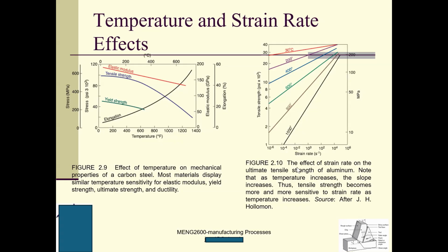So here is the strain rate. This is the tensile strength. The strain rate has a very obvious effect on the tensile strength also. If you have had a chance of operating some manufacturing machines, lathes, milling machines, all these metal cutting processes involve very high strain rates, right? If we want to model them, we need to use the Johnson-Cook model to accommodate the effect of strain rate.